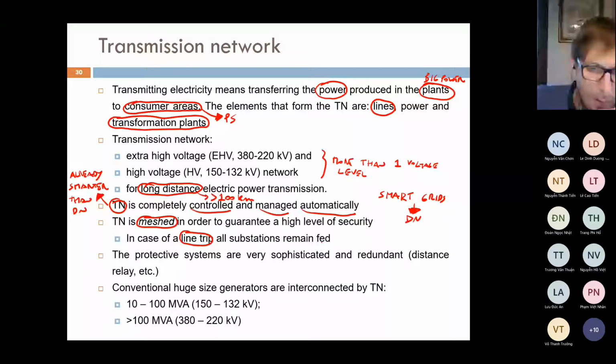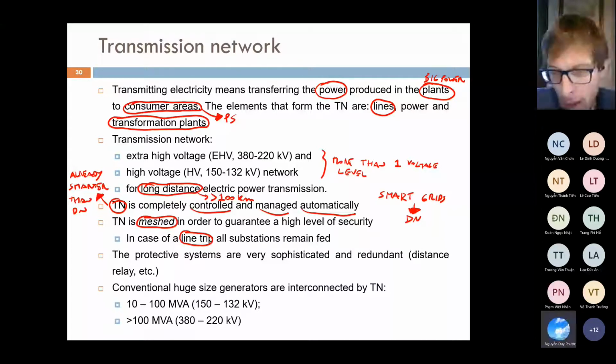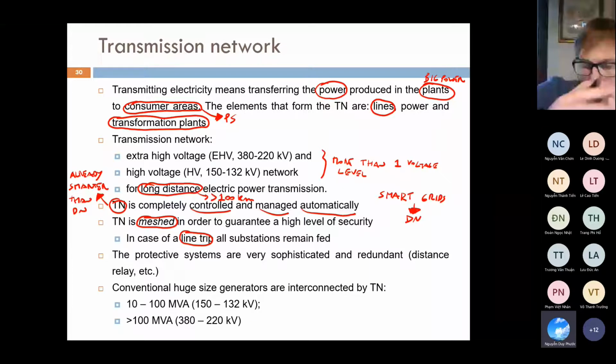If you think about your household, okay, if you have a problem with one of your devices, maybe you have a short circuit or an overcurrent, the switches that you probably have installed at the entrance, where the power system enters your household, trip, okay, so they interrupt the connection in order to extinguish the fault or the overcurrent, okay. Basically, when you have the trip of your protection device, you completely lose the supply of electricity to all your house, okay.